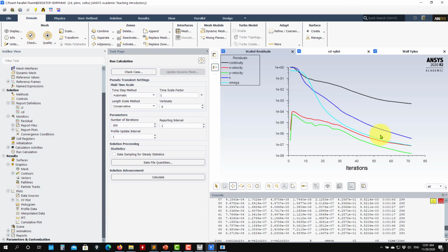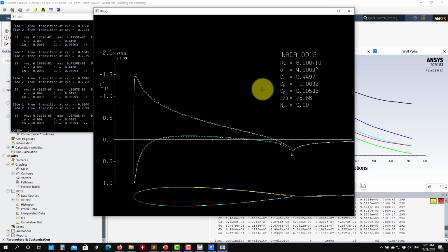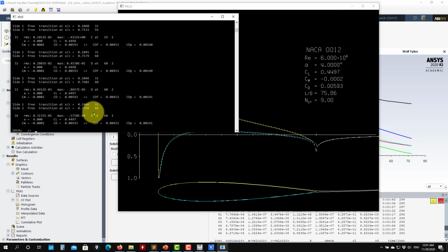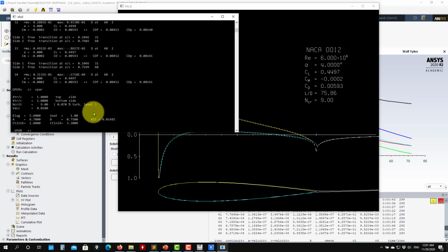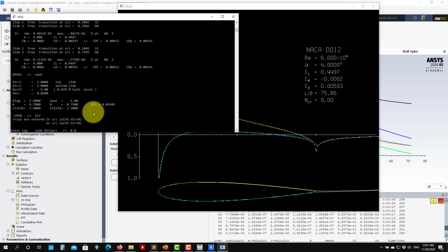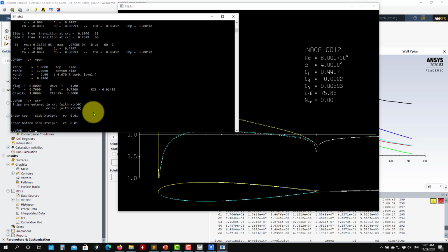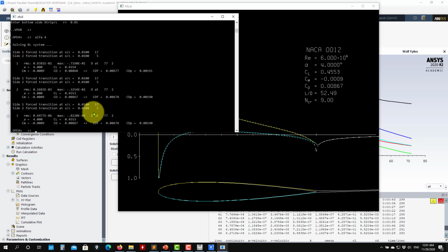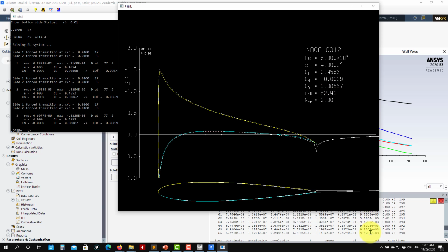Instead, when it comes to turbulence models, usually they assume the boundary layer is fully turbulent. So you can imagine that we have that mismatch due to that. If I change the transition parameters in Airfoil, I will probably get closer on CD, because I will try to set the transition to turbulence. So let's do that. As you go to the BPAR, we change this one. Set turbulence here and here. Now I will trip the turbulence at the beginning, and let me run again. See that now CD increased and it's getting closer.